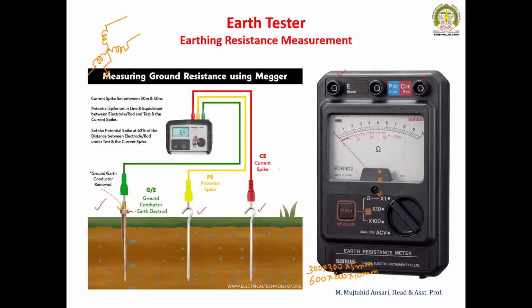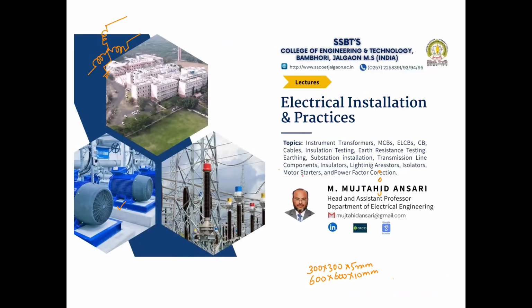The resistance should be less than 1 ohm for the neutral earthing, and 3 to 4 ohm is acceptable for the footing earthing or body earthing. If the resistance goes above 5 to 10 ohm, it means the earthing is not proper. Either we have to re-excavate or we have to recharge. In the dry season, it is necessary to pour water into the earthing to give proper results. So thank you. This is about earthing and earthing layout.